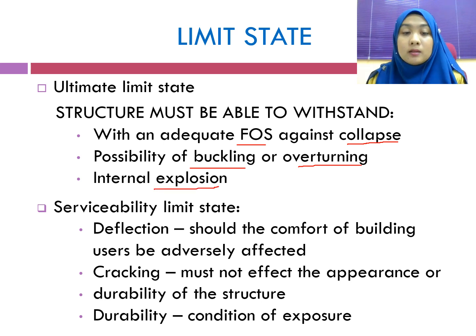So what happens at serviceability limit state? In terms of deflection, the comfort of the building users should not be adversely affected. It does not affect the users. And then the cracking must not affect the appearance of the structure, and also the durability of the structure depending on the exposure.